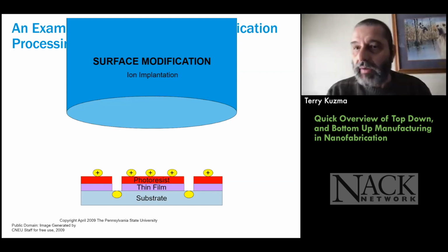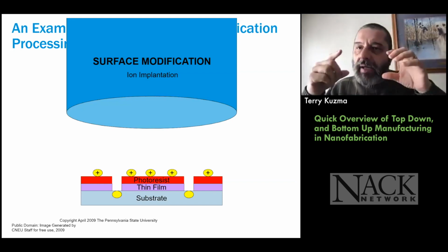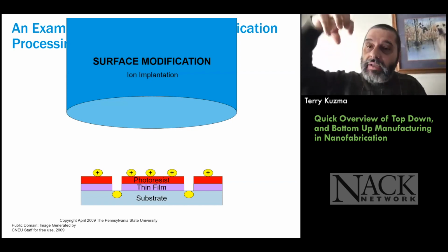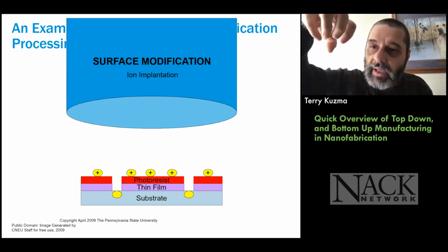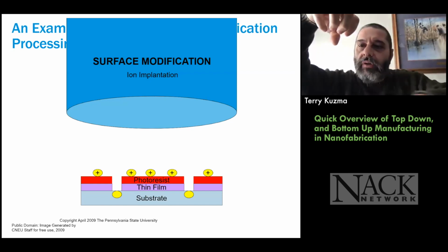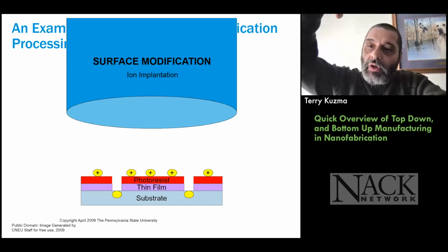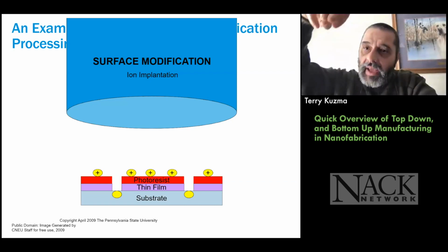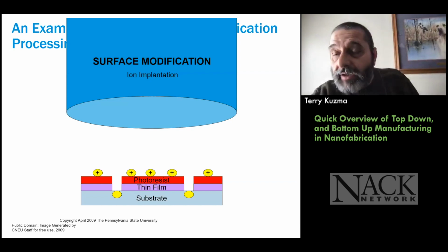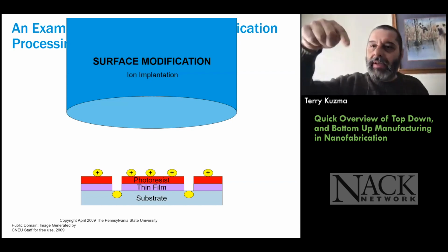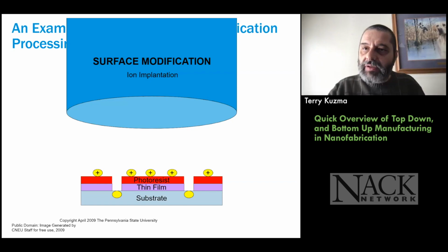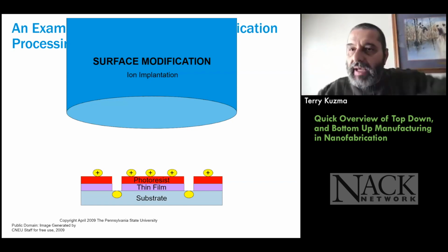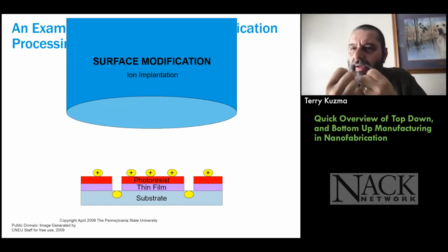So what's an ion implanter? We take a gas, we ionize it, which is by definition removing an electron. Now they're charged particles. Since they're charged particles, they want an electron more than anything else. We put a real negative field down here of electrons, and what they'll do is accelerate into that electrical field, just like gravity kind of stuff. They'll come smashing down with like 50,000 electron volts of energy, and they'll be able to go into the lattice. So it's like shooting a shotgun into plywood or something. So we're shooting this dopant into there. Does that make sense?